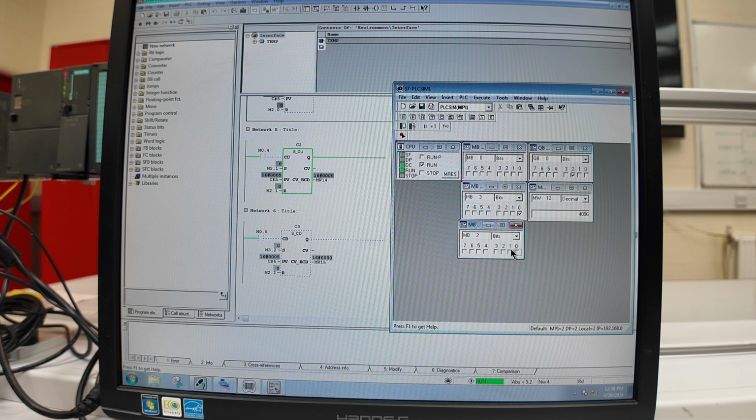And then you can reset the block the same way as the other one. Just put the reset pin high, the output is 0, and also the counting output gets 0 as well.